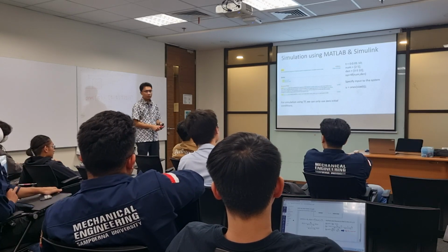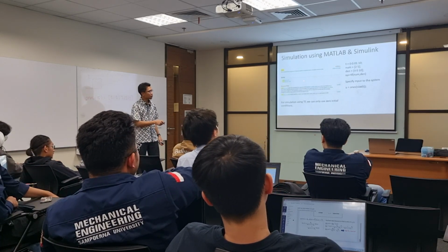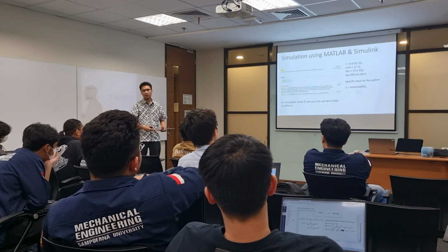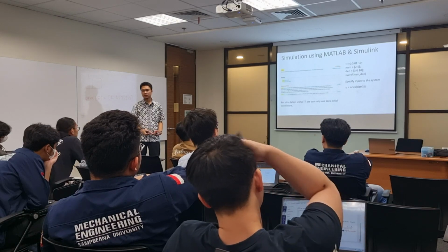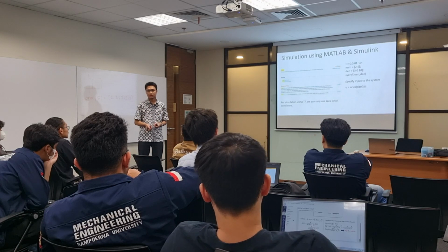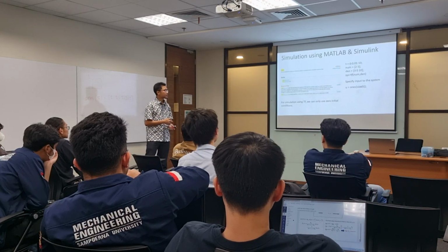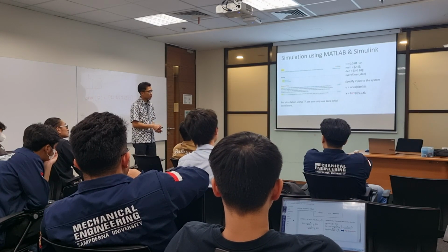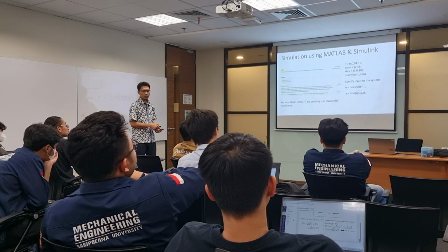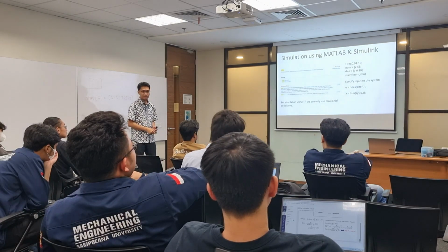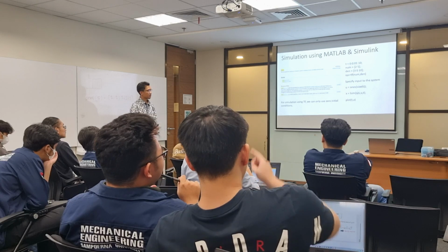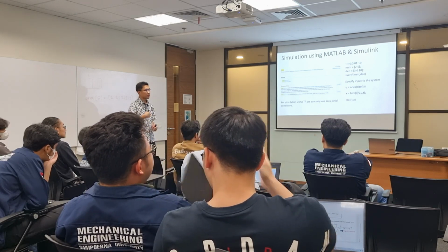We do that because LSIM wants you to specify u and t that have the same number of elements, the same number of points. If the numbers of points are different, LSIM will not accept it. Then you do this: x is equal to the output, and you can replace x with y, z, anything. This will give you the result, and then you can plot the result.